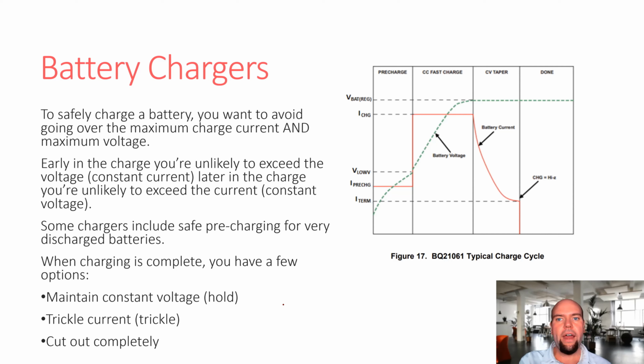If you overcharge a battery and exceed the maximum voltage, it's going to start to destroy itself. Remember that matrix that the lithium ions are trapped in; at a certain point, you will start to destroy things. You'll start to oxidize things, and you'll start to permanently break your battery.